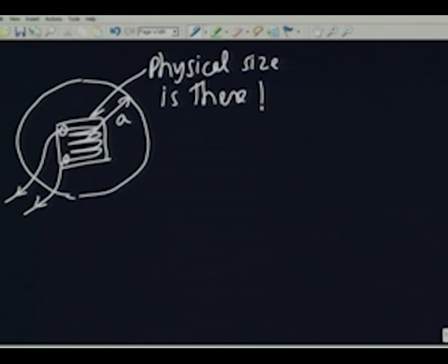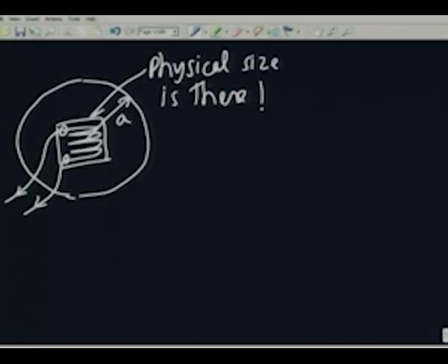It is not a small thing, you saw the picture I showed, it is quite a big thing. So, it is going to occupy a certain region on the diaphragm, which is not a point, but a certain area. Therefore, we can expect that the gauge is going to actually respond to the average value of the strain over the area of the gauge.